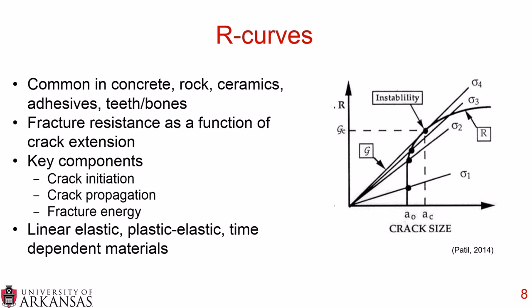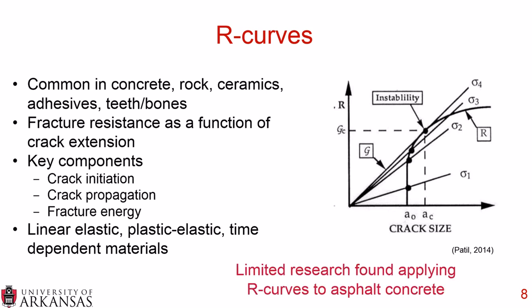A benefit about R curves is that you can calculate the R curves for linear elastic materials, for plastic elastic materials, and for time-dependent materials like viscoelastic materials, which is what asphalt concrete is. But as I mentioned, there's been very limited research found in applying these R curves to asphalt concrete.